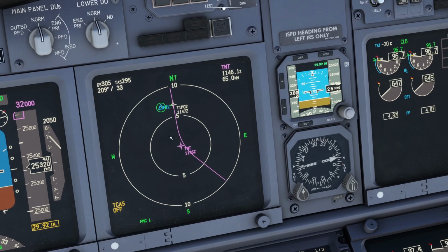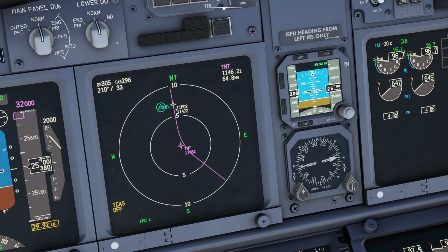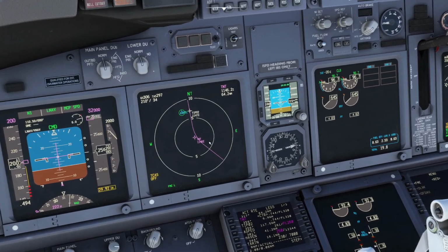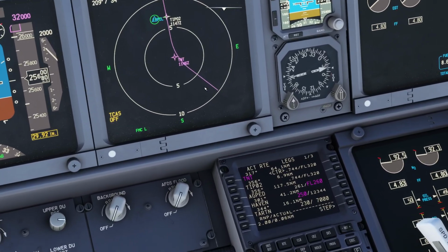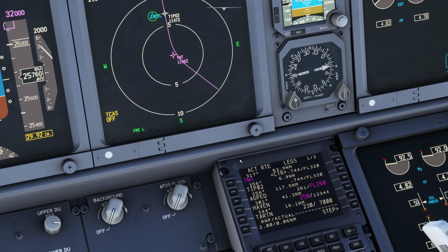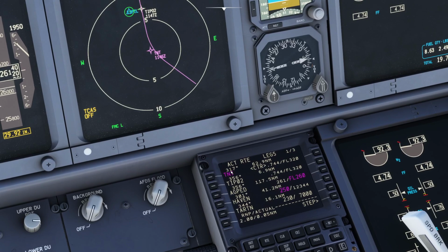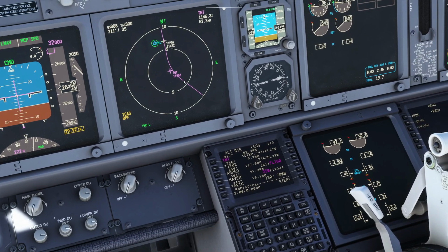So it's done a vector waypoint for us that's on our route, so we could use it as a turning point perhaps. Okay? Another thing we might want to do, we're flying towards TNT at the moment. When you're looking at your flight plan, you'll notice that the aircraft automatically figures out the route between the waypoints. So for the one you're actually flying towards, you can change that route in. So we can change the radial. So we're going 317 degrees into TNT at the moment.